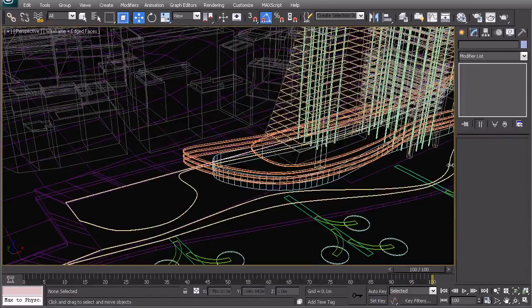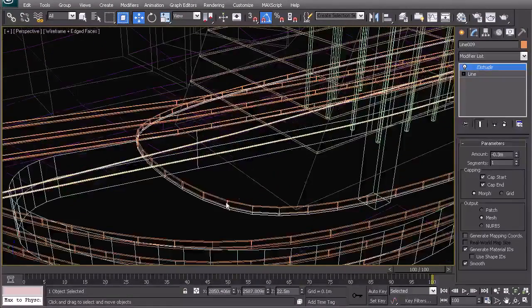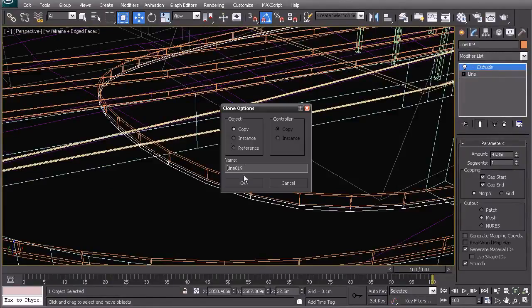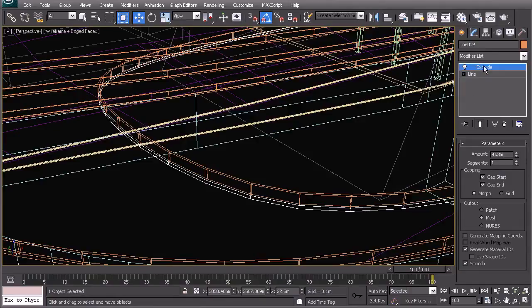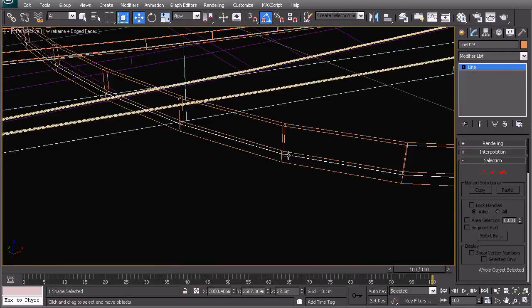So what we're going to do now is we're going to add some planting and trees to here, some planting along this band, and we're also going to add some planting to this area over here on top of the podium. Now for that area on top of the podium, what we need to do is we can go Control V for this top slab, we can copy that, we can remove this extrude modifier, and the planting strip is right here.